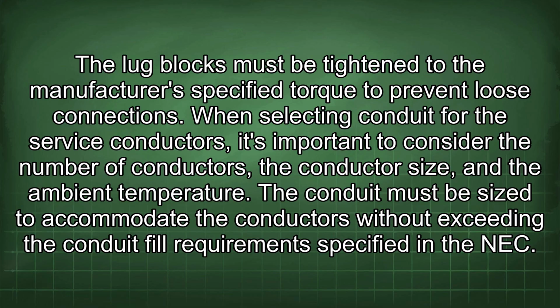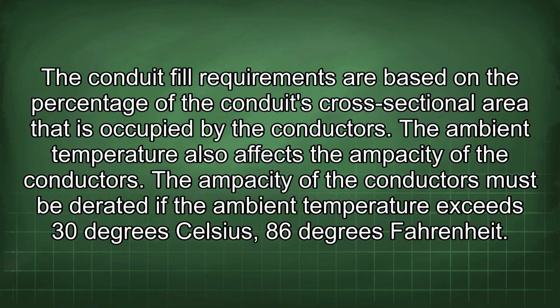When selecting conduit for the service conductors, it's important to consider the number of conductors, the conductor size, and the ambient temperature. The conduit must be sized to accommodate the conductors without exceeding the conduit fill requirement specified in NEC. The conduit fill requirements are based on the percentage of the conduit's cross-sectional area that is occupied by the conductors.